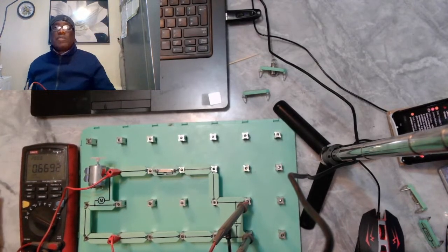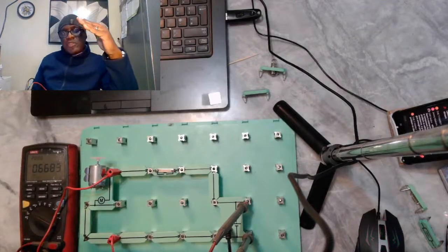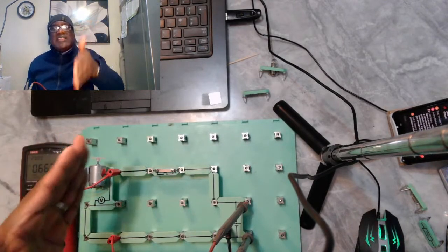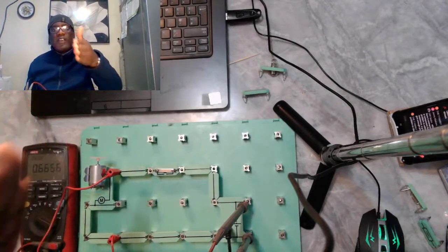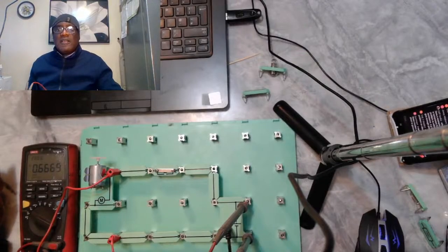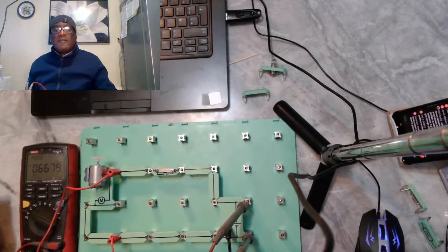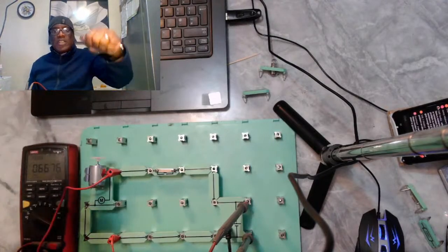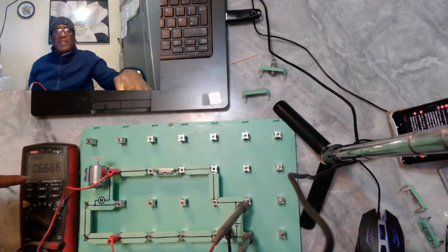If it's giving you 0, then you need a manual to know how many sensors are connected to this 5 volt. Say the manual tells you 5 of them are. Then you go to the other 4 and disconnect them one by one, watching your meter.